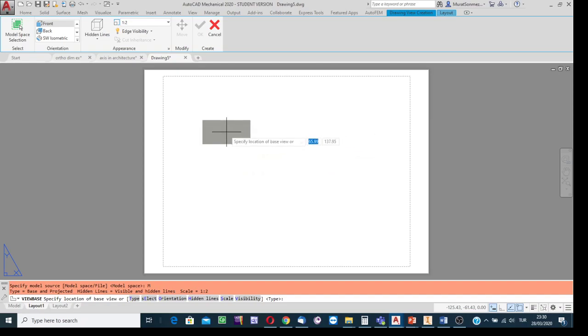I think this is the wrong side view, so change the orientation to be able to create the sectional view. First we must create the view on which we have the edge view of the cutting plane, since we need to define the cutting plane line.